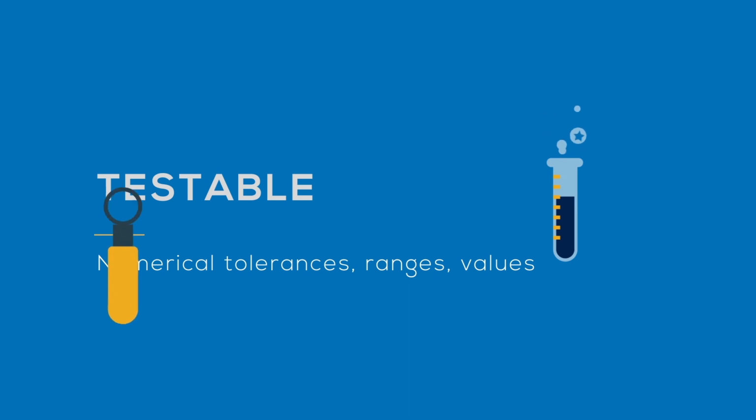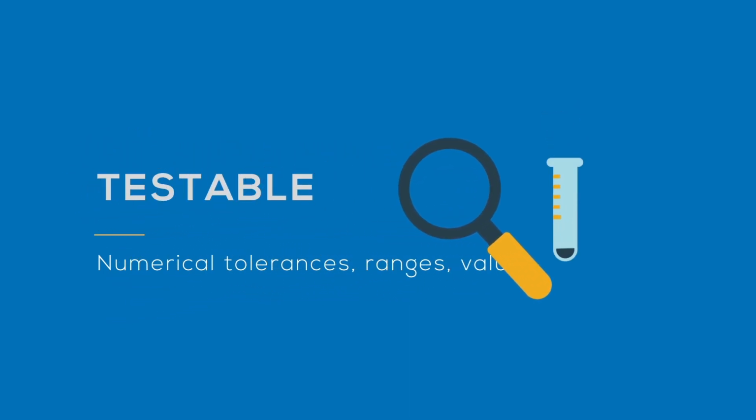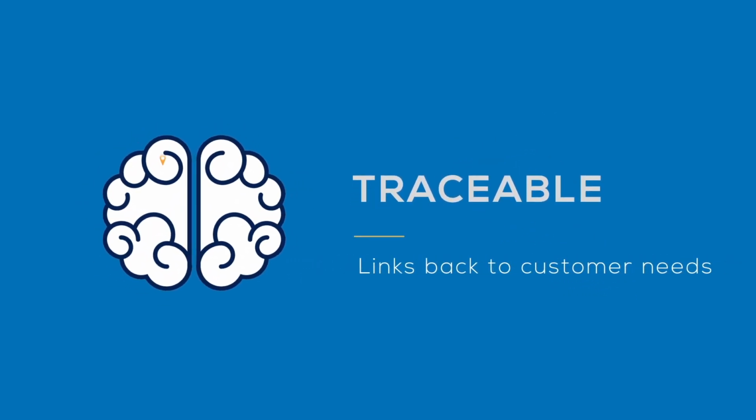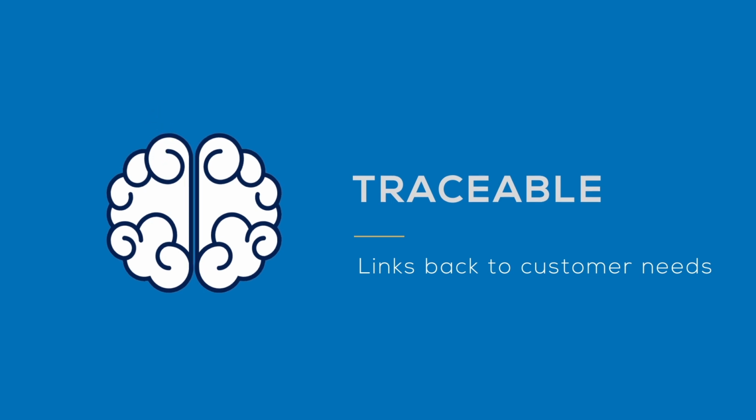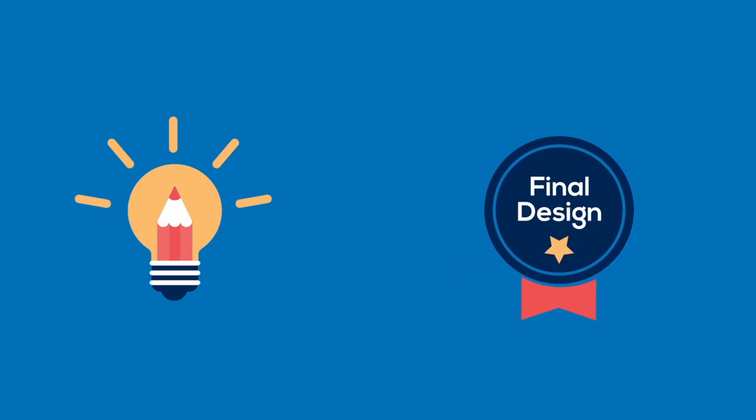These requirements can be measured in order to determine if the design goals are met in the final product prototype. Finally, the device description should be able to be traced back to the rationale from which it was derived. That is the statement of intended use, and traced forward to its implementation in the product design. Think of the device description as a bridge between the idealized statement of intended use and the finalized design for manufacture, which will be the endpoint for the product stage.